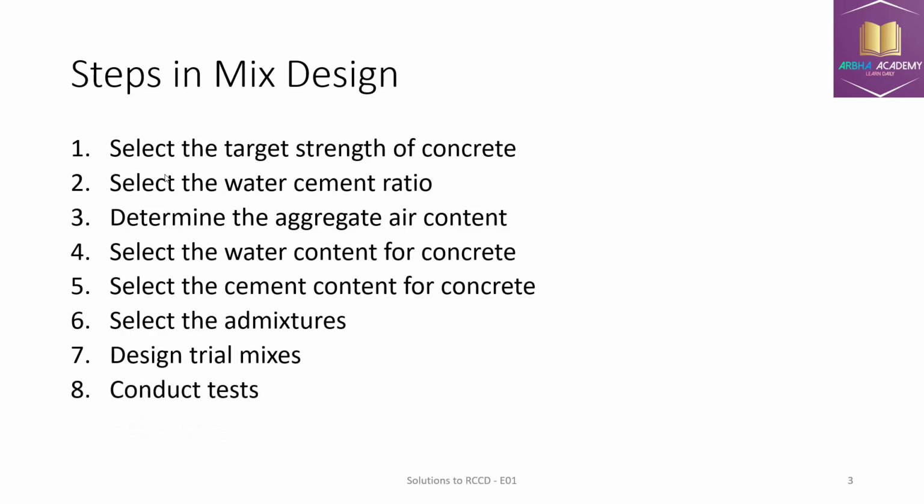After that, we need to conduct tests. For the tests, cubes are to be cast, cured for 28 days, and then tested for the compression test. Once the compression test is done, based on that we need to verify whether we achieved the appropriate strength of the concrete or not.